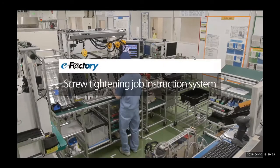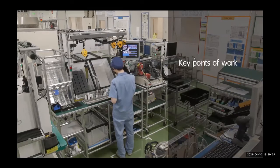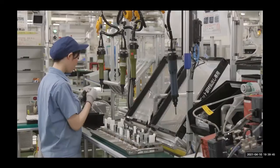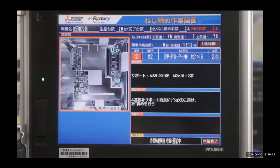Now, let's take a look at the screw tightening job instruction system. There are two key points in the work: using the correct parts and installing the parts according to the correct method. In the screw tightening job instruction system, the indicator screen in front of the worker displays the type and number of screws and the type of electric screwdriver to be used.